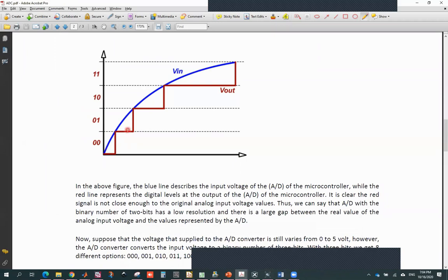So you have an analog input, and you have to sample it. For example, at this time you sample the analog input, and let us say the voltage level here is 3 volts. You have to quantize that input into a discrete level. 0 0, 0 1, 1 0 and 1 1 are the discrete binary levels. So how do you quantize the input signal into its discrete or digital equivalent?